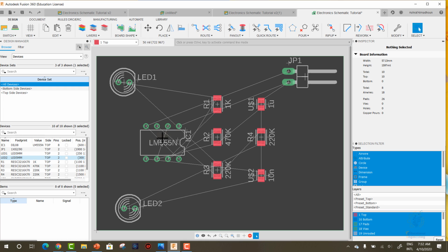But before doing this, to make sure that our positioning and wiring is correct on the PCB, go to the pour and click pour polygons. As you can see, some of the wires changed their location. I will press Ctrl Z so that you can see what happened. As you can see, this wire was going there and now it's coming from this point. So it's here now. Once I click here, it will change its position to here. As you can see, this is an easier track for the route.